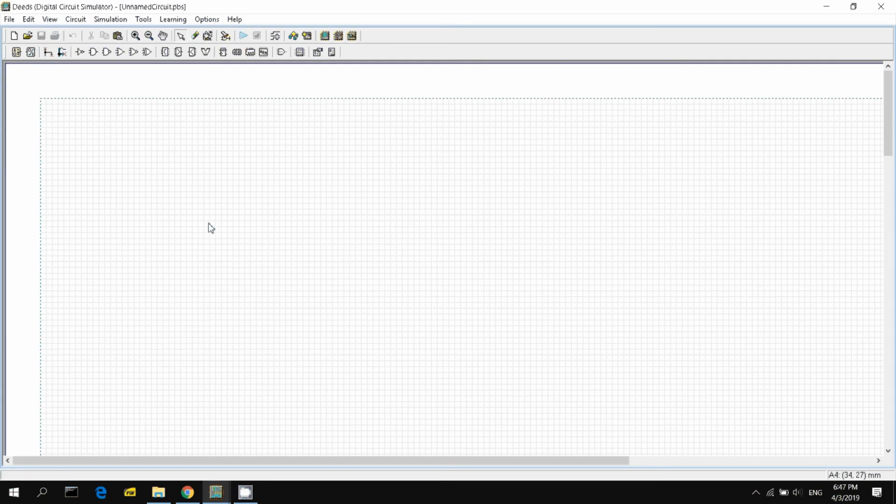So now I'll try to cover some of the basics first. If you want to construct a wire, just right click and click wire. You choose any spot. They have a grid system, like X and Y coordinates. You choose a spot and then you click. After you click, you move around and select another spot, but it must be on the same vertical or horizontal line. So either here, let's say I choose here. Then I can continue.